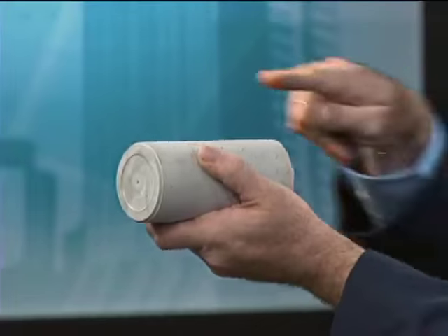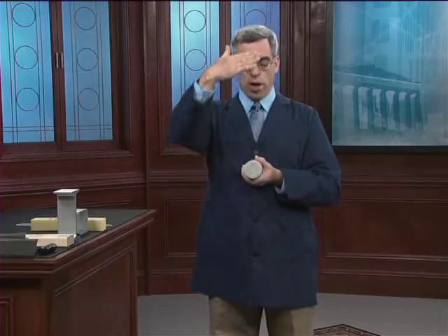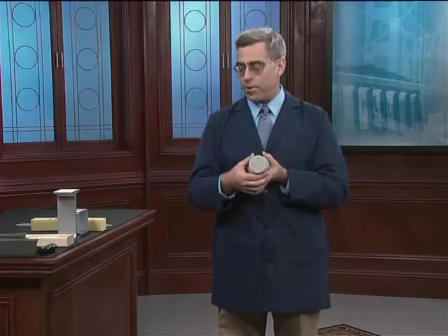Okay, so what's a cross-section and what's cross-sectional area? Well, the cross-section of a structural member is really just the two-dimensional shape that's formed by cutting through the member on a plane perpendicular to its long or longitudinal axis. So if this were a concrete member, it's cylindrical in shape, the long or longitudinal axis of the member is running this direction, and when I make a cut, I expose this shape, it's a circle, and that circular two-dimensional shape is the cross-section. The cross-sectional area then is simply the area of that circle, pi r squared.